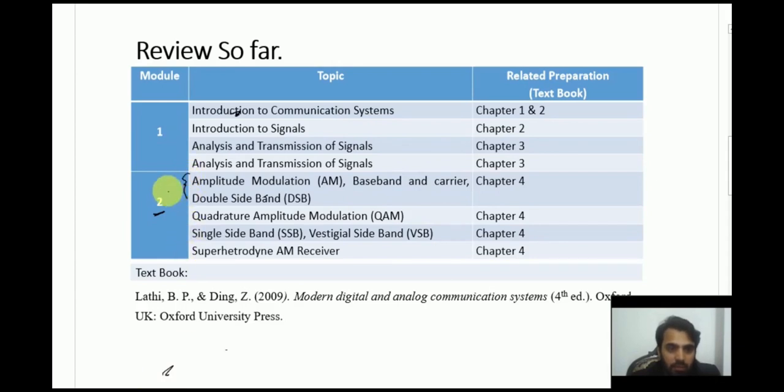these two are basically bandwidth inefficient, right? Inefficient in a way that if our original bandwidth of the message signal is 1B, B is the bandwidth, the transmitted signal, or let me call it S of t, would be basically 2B. So they are bandwidth inefficient. So then we moved on towards the schemes which are bandwidth efficient.